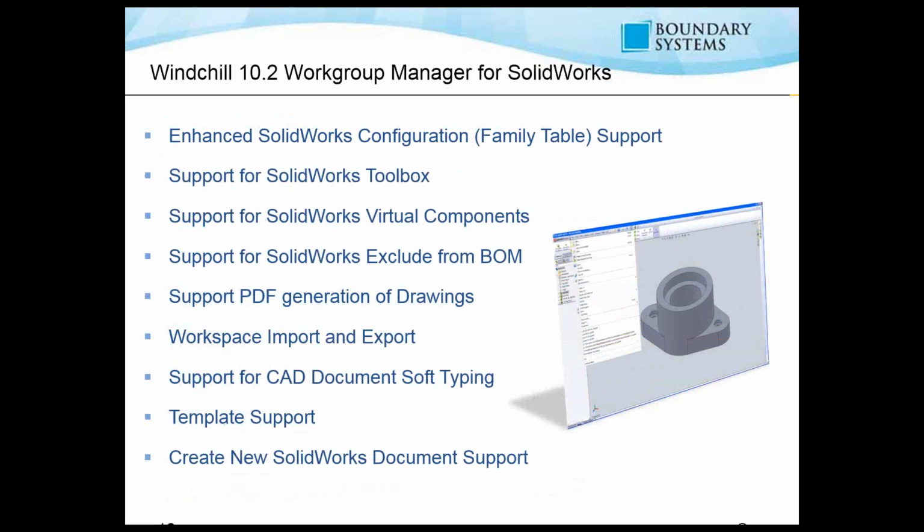So the Workgroup Manager for SolidWorks, once again, enhances SolidWorks configuration. Once again, it does support family tables. Family tables have always been an issue, just period, in management, but Windchill manages those very well, whether it's Creo's family tables or SolidWorks family tables. It also supports the SolidWorks Toolbox, SolidWorks Virtual Components, and the exclude from BOM option from SolidWorks, of course.